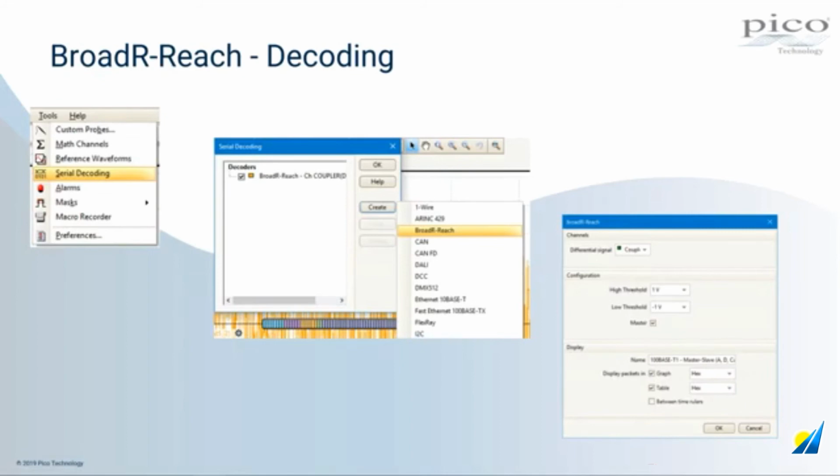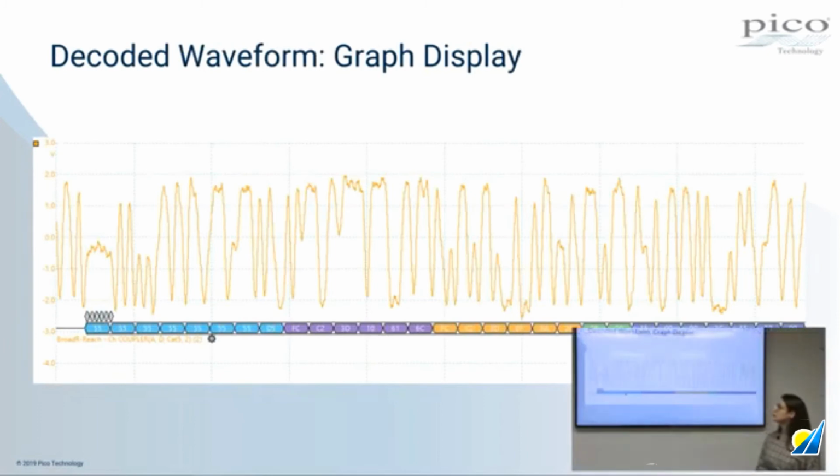So that's your PAM3 digital bits. And also you need to specify whether the decoded signal is a master signal or a slave signal, because they are using a slightly different scrambling technique. So that would give a hint to the decoder algorithm which one to use.